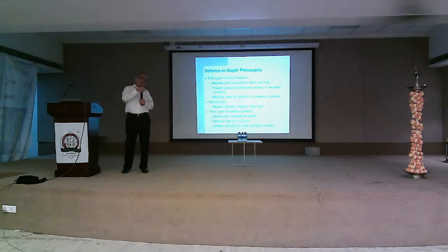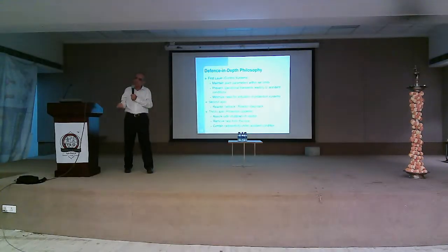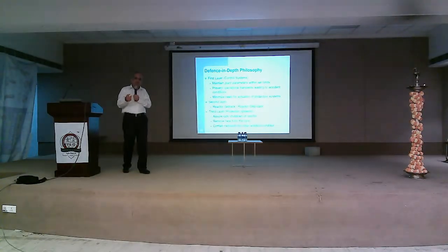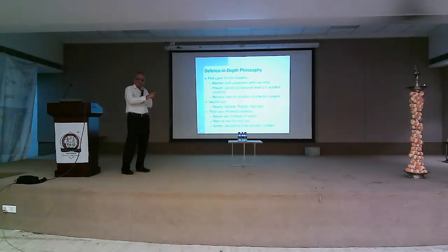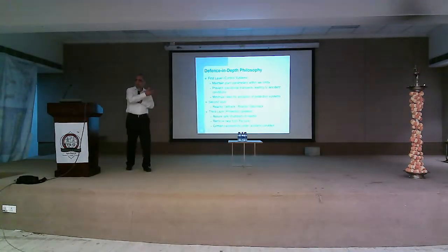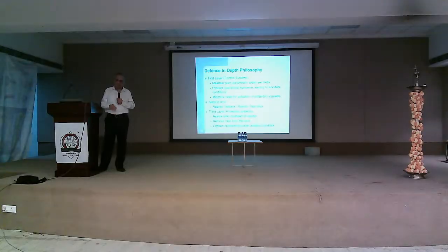For that purpose they had put up a wall of around 12 meters height to take care of tsunami. But this time the tsunami was beyond 12 meters. And water came inside, and all the shutdown electrical equipment was covered with water, and thus even shutdown cooling could not start, which led to the accident.